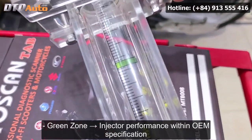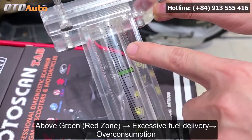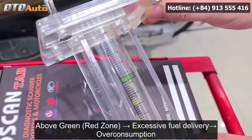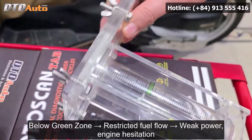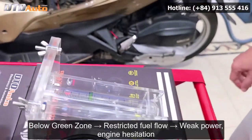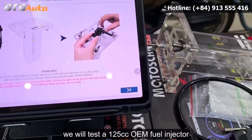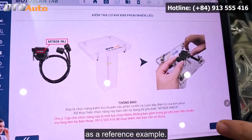Green zone, injector performance within OEM specification. Above green, red zone, excessive fuel delivery, overconsumption. Below green zone, restricted fuel flow, weak power, engine hesitation. In this demonstration, we will test a 125cc OEM fuel injector, purchased from Honda, as a reference example.